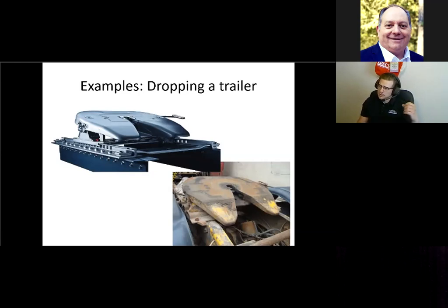the reports, where each assembly stage has reports like we took these parts, we took these parts. So you can basically trace it all the way down to its individual parts and when they went on and who signed off on them. And long story short, we find in these reports that nobody signed off or checked the remaining bolts. So basically the fifth wheel is attached with these 4 bolts, and then it goes on to a different process that then does the final assembly of those bolts. Nobody had actually signed that at all.